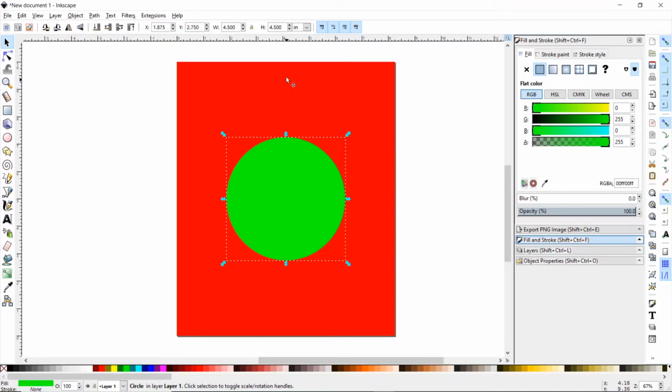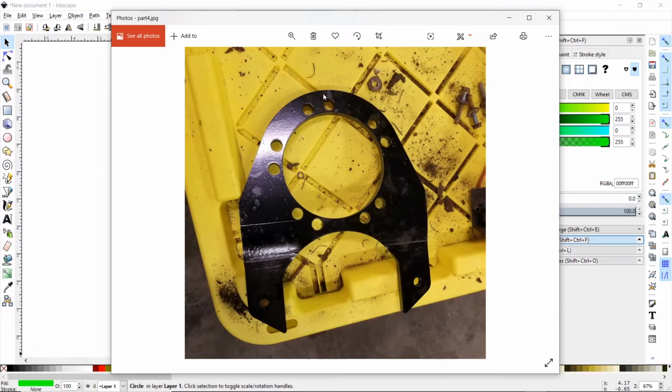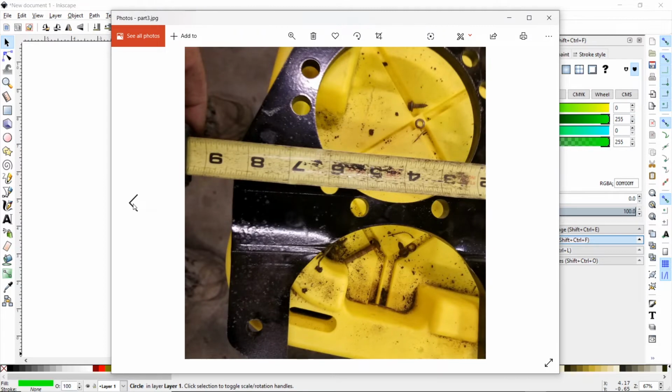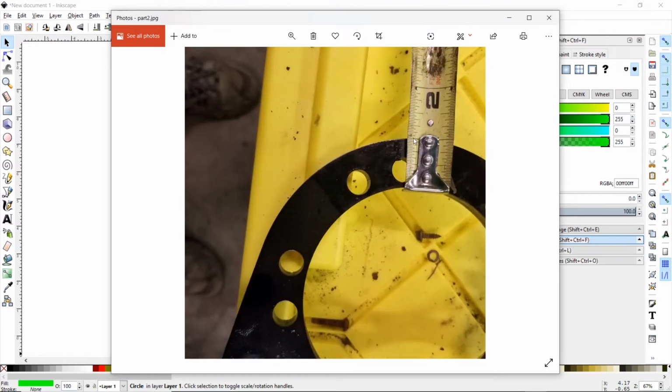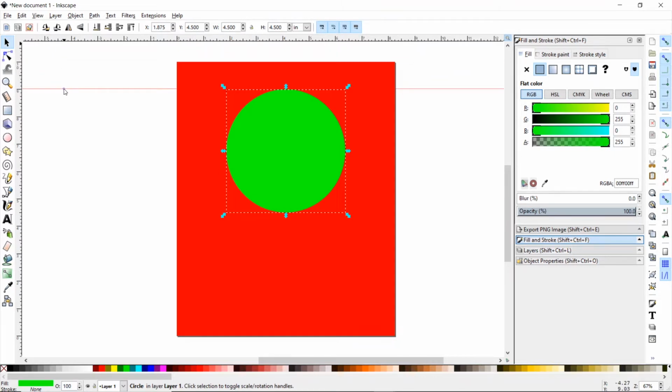Now we have to move it all the way up to the top to get it placed, or somewhere towards the top. Let's take a look and see. Okay, so that's the very top. It's whatever the thickness of this is right here, that the top of this needs to be down from the top. So let's go and see if there's one showing. Okay, right there. It looks like 1 inch. 1 inch is what that band needs to be. So, and this is 4.5 inches, and that was 10 inches. So we need to be at 4.5 inches from the bottom on this one. Let's go to 4.5. Yep, there's 9 inches coming across right there. You can see that goes right across the top of that bounding box.